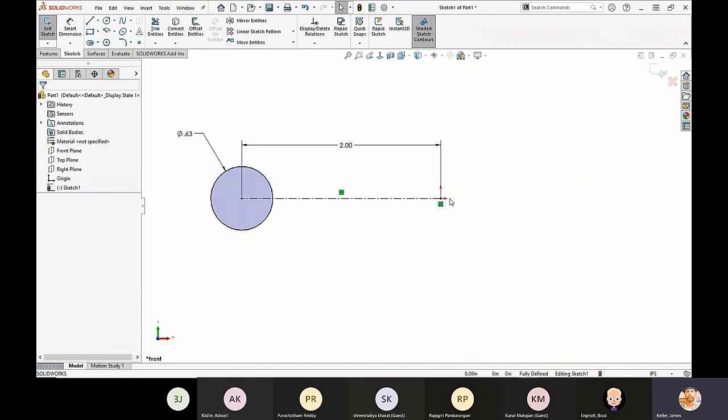And that's the best way to start a sketch or assembly, is from the origin. So you are starting everything from a fixed point. Again, that's part of your design intent. And I chose to have the origin directly in the center of my part. As we build it, you'll see that this origin is going to be right in the middle of a whole feature we're going to create down the road. So it pays to think about how you want your parts created before you get in there.